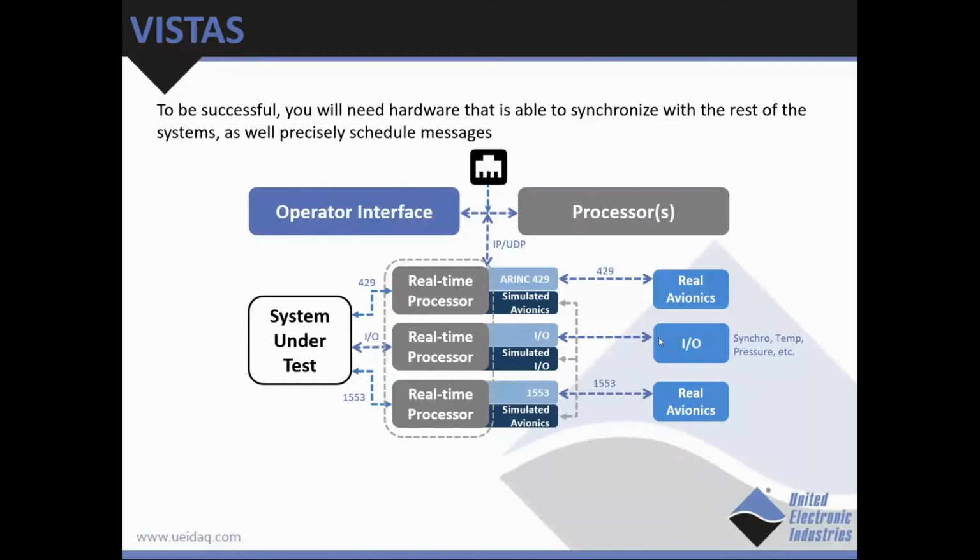Additionally, it is possible to create a virtual bridge between the test setup and an avionics device, which could be located in some other remote location. To do that, one set of UEI Avionics interfaces talks to the device and another set talks to the test bench. Two sets are connected via local or global TCP/IP network. Although the virtual link between the emulation and the emulation hardware could have a latency or jitter, if it's set up correctly, the emulation hardware can use the hardware schedulers we discussed to solve those problems.